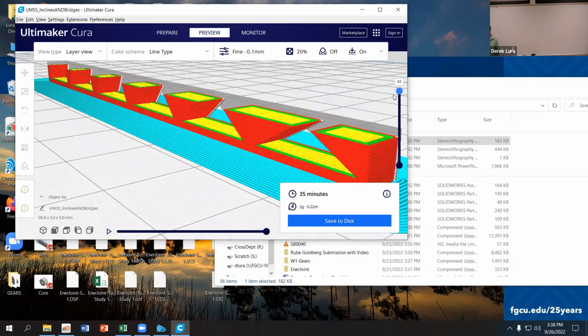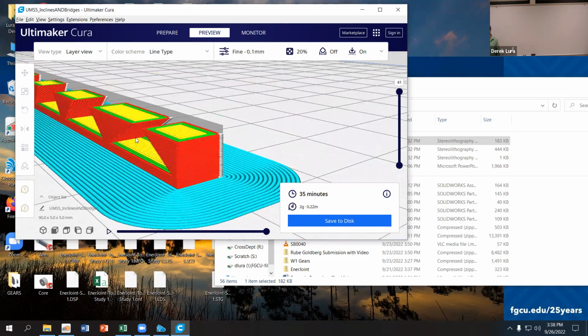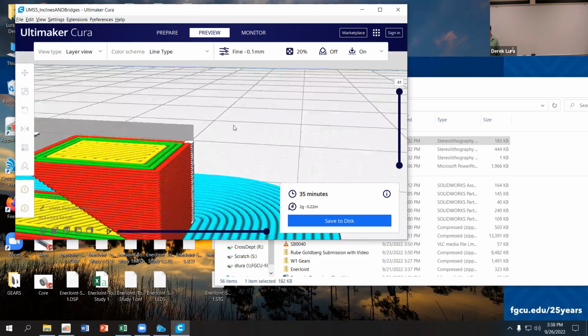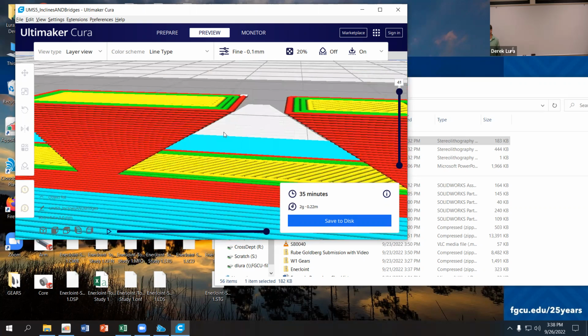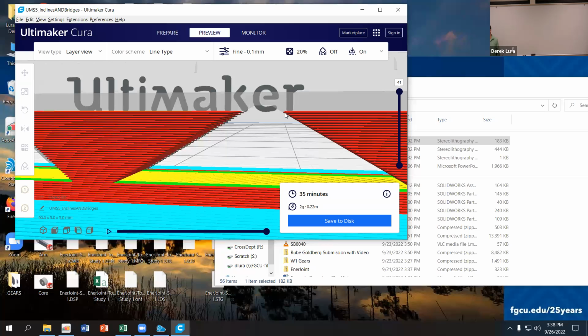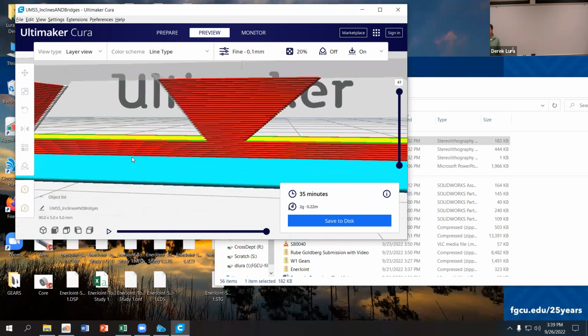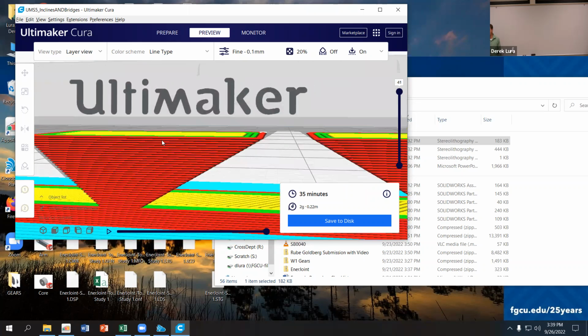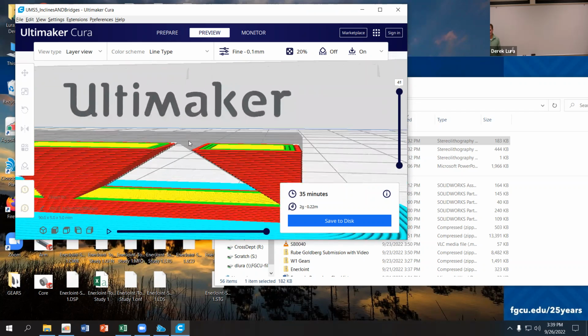And you can see that each of these layers here, especially on this really high incline, the 60 degree, doesn't actually have anything supporting it underneath. So there's an amount of material here that's being extruded out past the edge of the previous layer. Generally, as long as you have some amount of overlap between the layers, so the nozzle is not hanging over nothing, you can get a reasonable overhang and still get good quality prints. And then once you get past this point here, when we get over here, that's when you want to start having supports underneath the part.